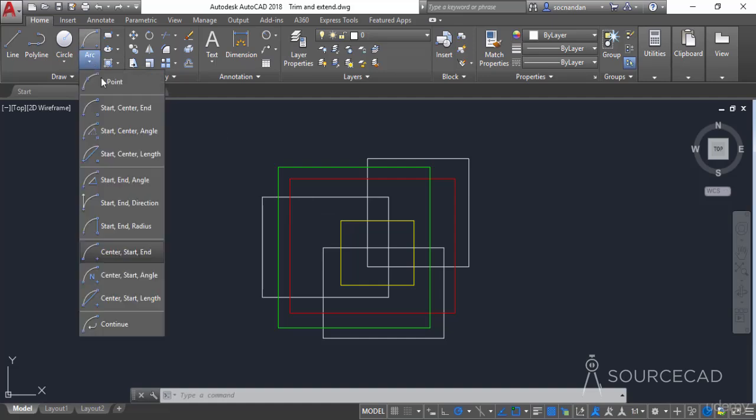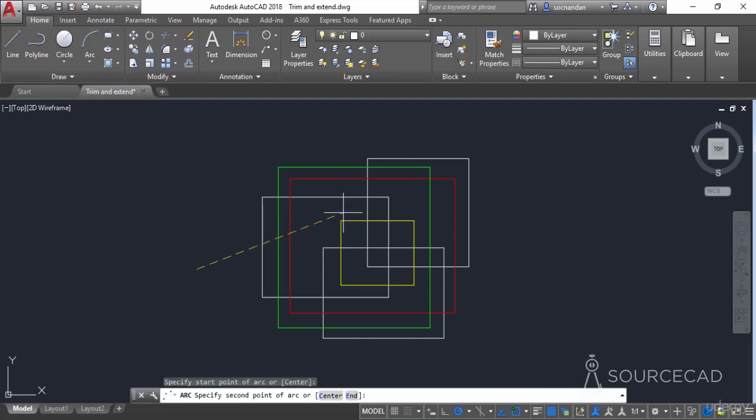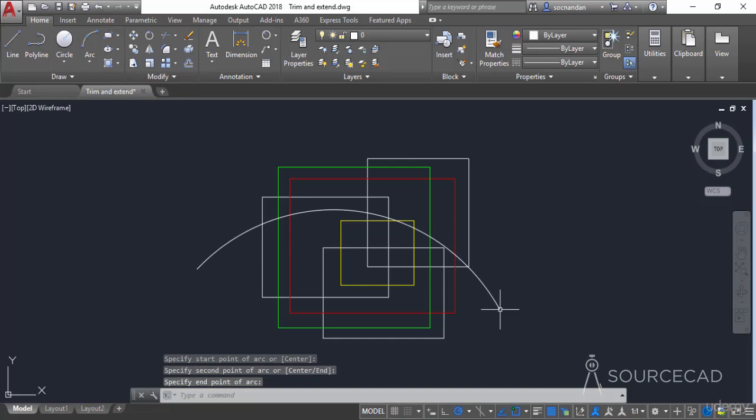So if you create an object, let's say that we create this 3-point arc somewhere inside this object here, just like this, and we want to trim this object. So this will only be trimmed if a next boundary is found. So let's select the trim tool, press enter, and now I'll click somewhere inside this geometry and I'll click this part, and the part has been removed.